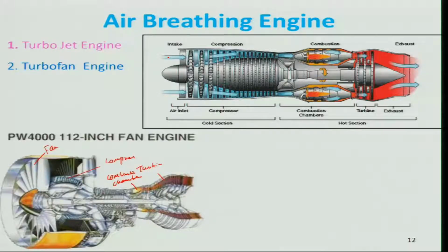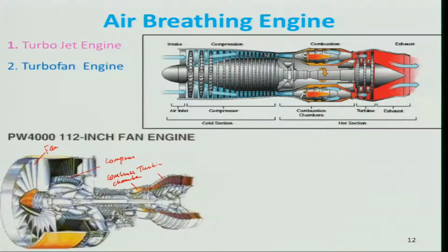Actually, in the air intake, the total temperature we assume to be remaining constant, because we say that heat losses will be negligibly small. Therefore, the total temperature stays the same. The total pressure, of course, will decrease because of some fluid dynamic losses from the aerodynamic point of view. However, there will be an increase in total pressure in the compressor.